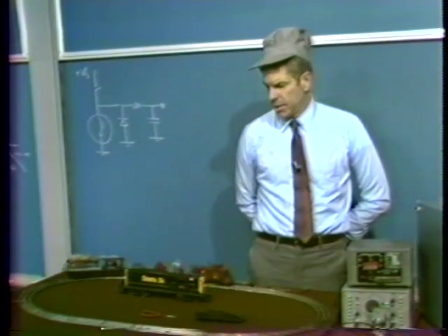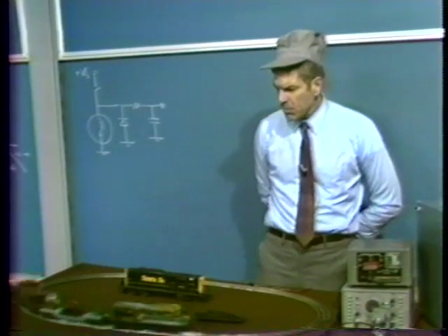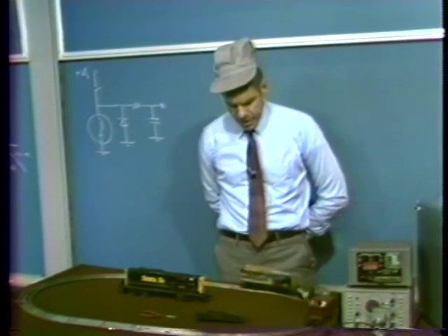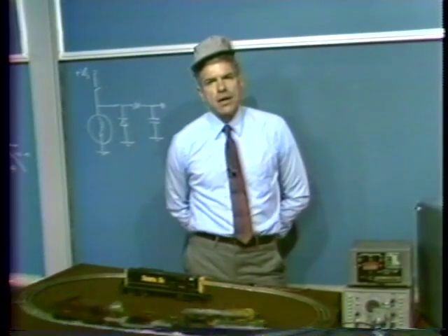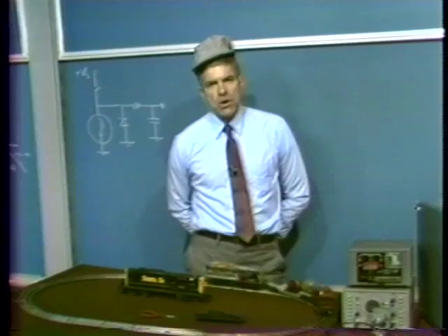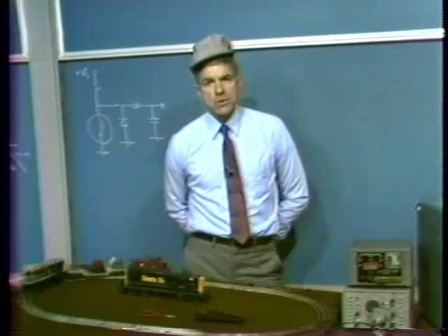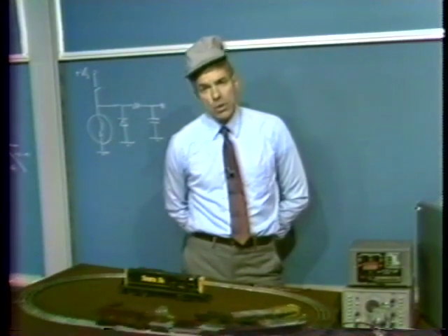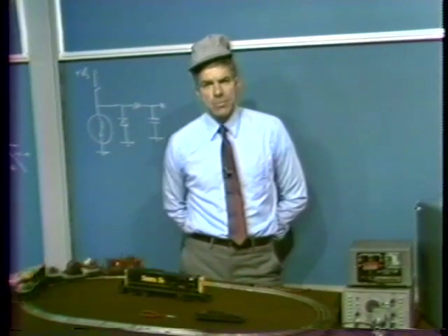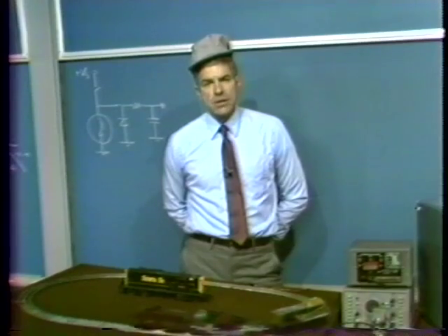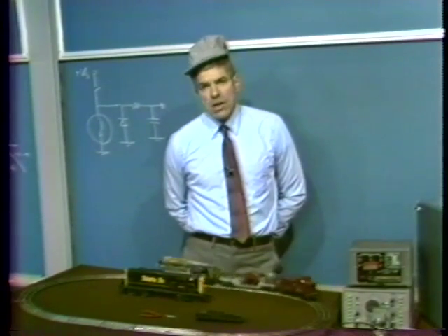The difficulty there, of course, is that of heat sinking. If you build a linear power amplifier, as you recall, it sort of looks like a variable resistor between the power supply and the motor or whatever load you're driving. It's a problem that's common to audio amplifiers or any other kind of amplifier. If you build a true linear amplifier, it's lossy.